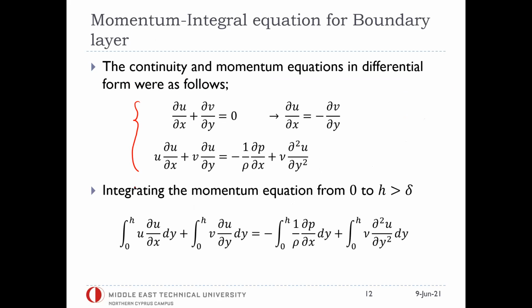He tried to reach a simple equation, but now the equation directly written for these integral quantities, like theta, for example, like delta star, for example. So that's the purpose. Can we reach one simple, if possible, ordinary differential equation written in terms of these integral quantities? So if I can solve directly one equation, the direct result that I get are the quantities themselves, instead of these f primes and everything.